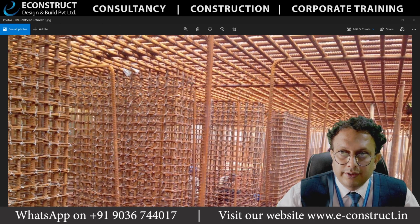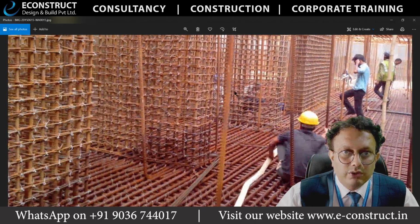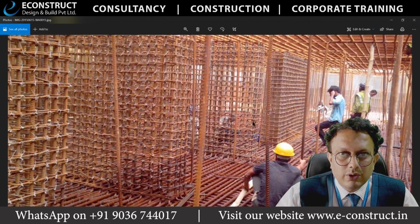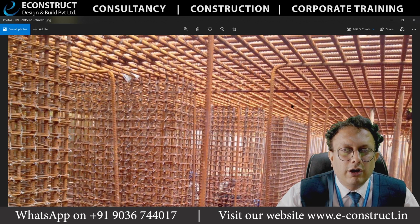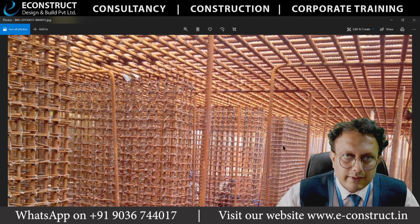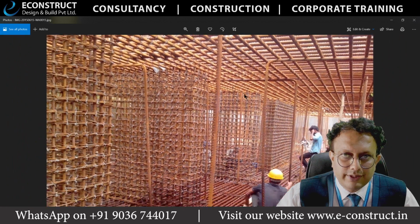Alright? Okay, so massive works only will be done. So you can see that the rebars are there, and we call these spacer bars or chairs. Such kinds of words are utilized in industry. The purpose of this is to maintain the spacing between the two rebars. So this is the raft.